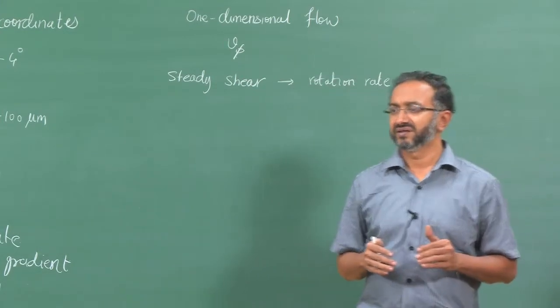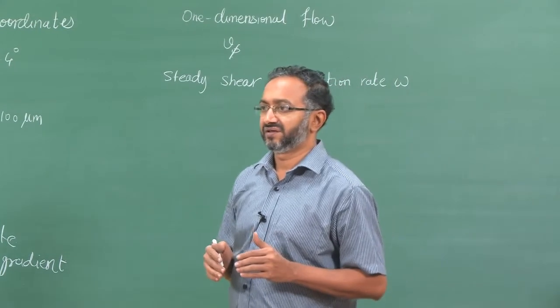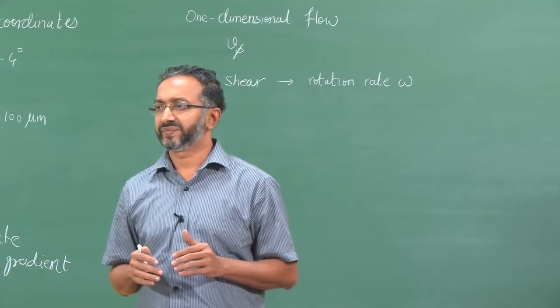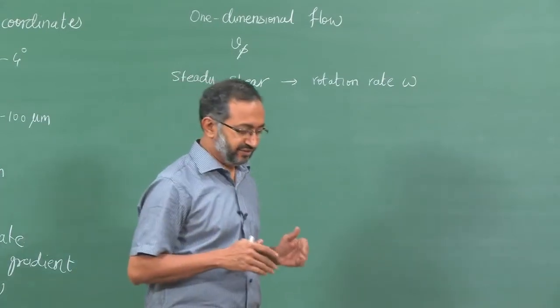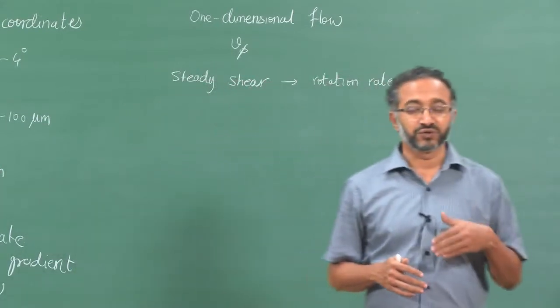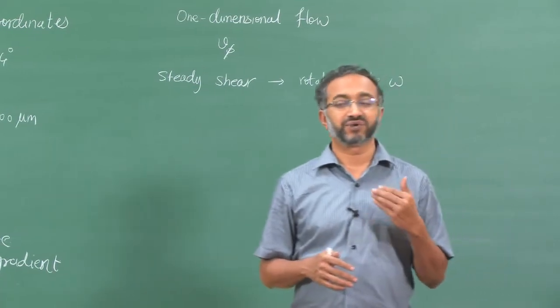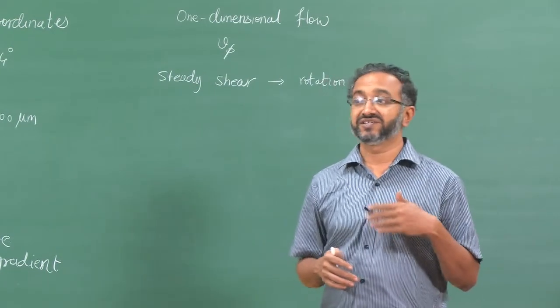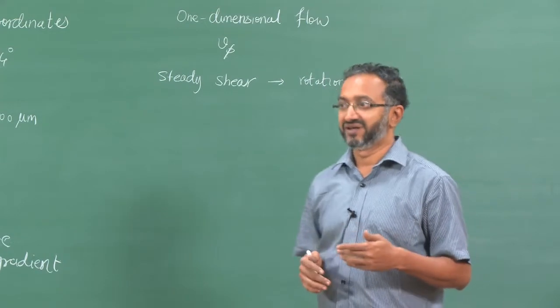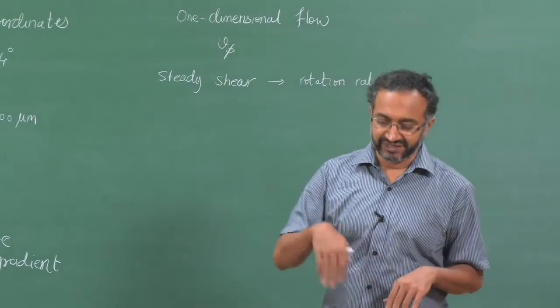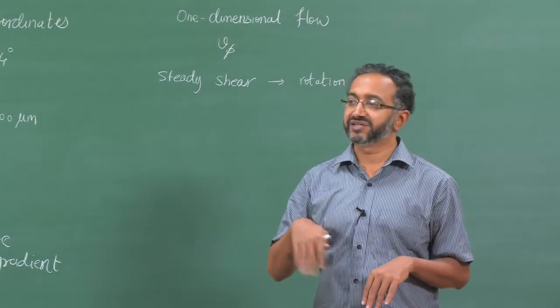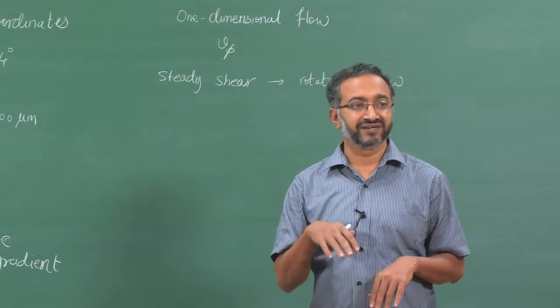At low shear rate, the velocity at r distance will be almost 0. Yeah. So, one of the responses is to first think about under what condition radial velocities might arise in the fluid. For example, if I ensure that I am only moving in the theta direction, it is safe to say that the fluid will also move in the theta direction.